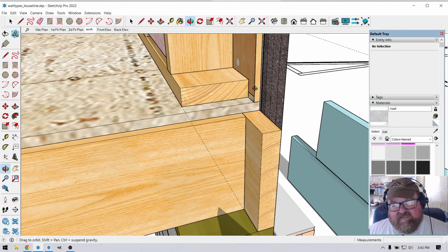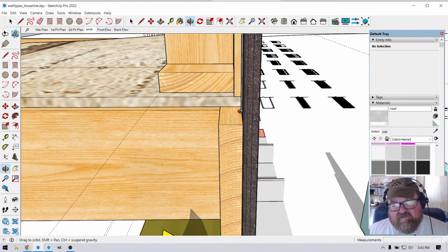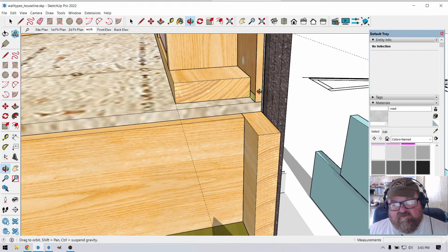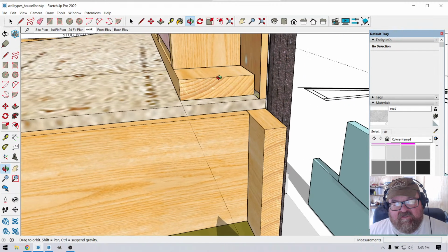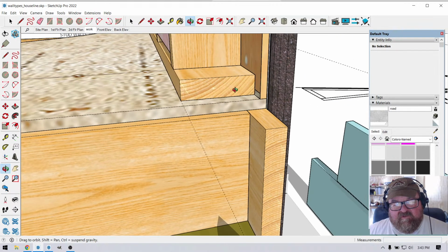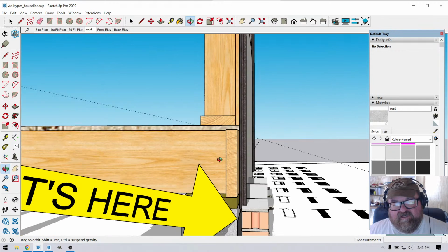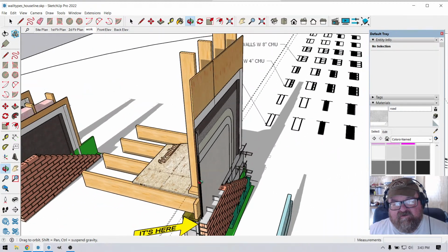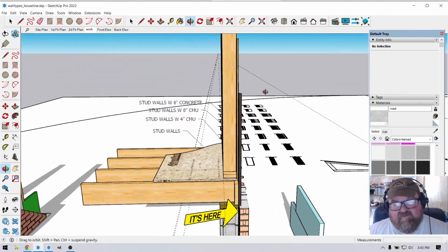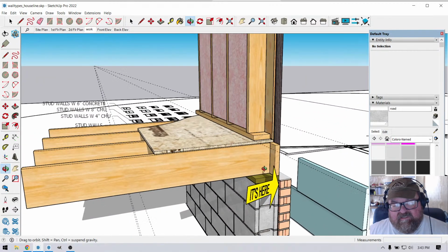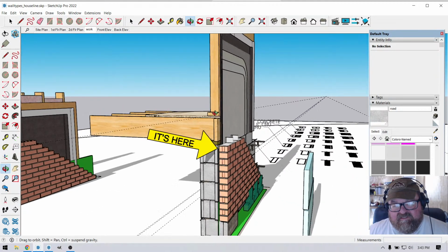The reason the sheeting sits flush with the house line has more to do with the function of the sheeting and its structural rating and how it creates a shear wall, and how it has to be nailed to the bottom plate and not lapped over the band, because that creates a situation where you can't nail the sheeting in between the studs. We talked about a lot of that kind of stuff, just talking about the house line.